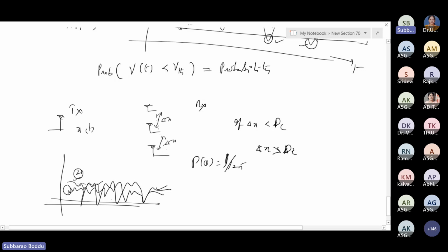It means that by virtue of getting independent signals in these two branches, or you can say many branches, of course, here there are many receiving antennas, the probability of the received signal strength going below the threshold becomes very low. So this is the advantage due to diversity. This is called the advantage due to diversity.